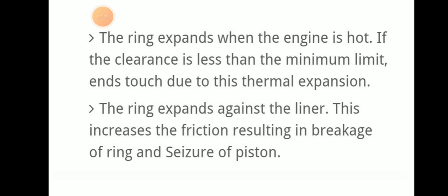The ring expands when the engine is hot. If the clearance is less than the minimum limit, the ends will touch due to thermal expansion. The ring then expands against the liner.